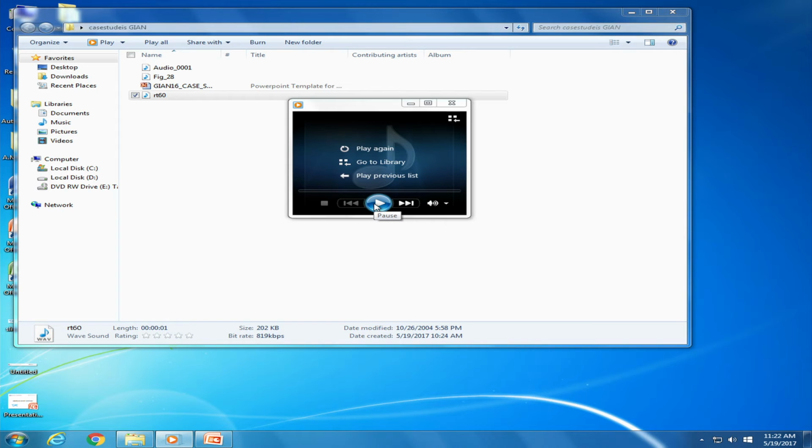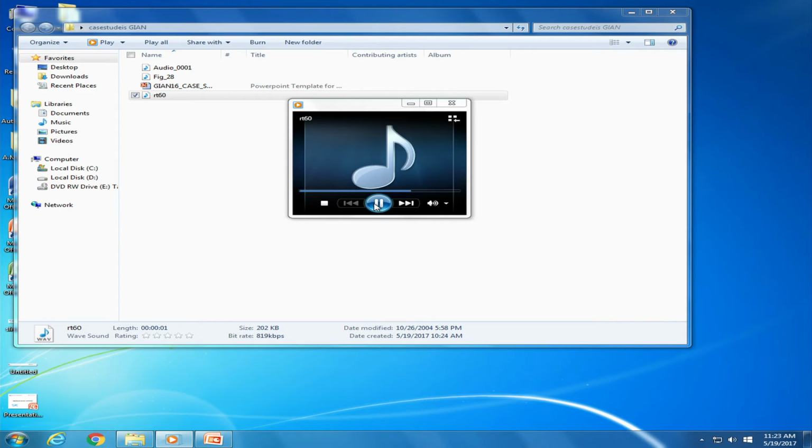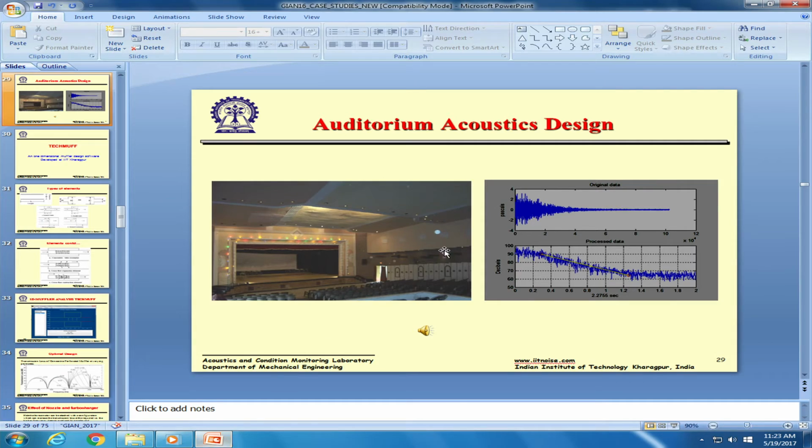So this is the high impulse, and then we switch it off. So the decay could be found out, that 60 dB drop could be found out. If it's not 60 dB, we can always extrapolate, as Professor Bolton was mentioning yesterday. Okay, so this is the decay, and then you can find the RT time for this auditorium, and then you can play around with the materials.